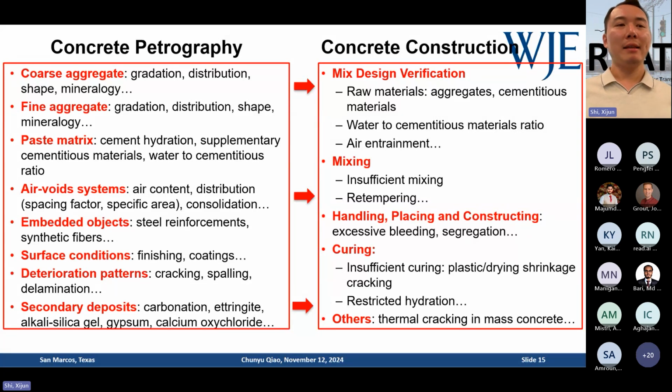When I say that it's an estimation, it's because it is very, very difficult to give you a very accurate W/C or W/CM estimation or evaluation, because there are so many factors that can play a role and make it difficult to properly assess it. But a good petrographer should be able to identify a proper range for it.